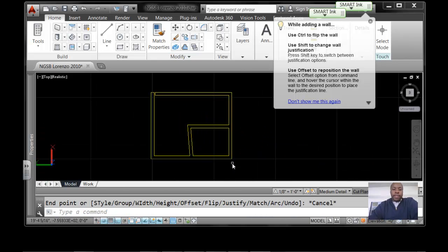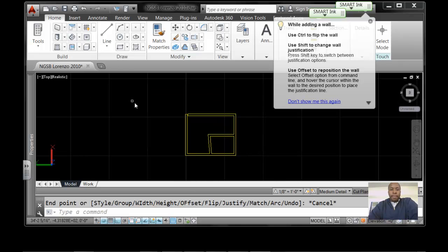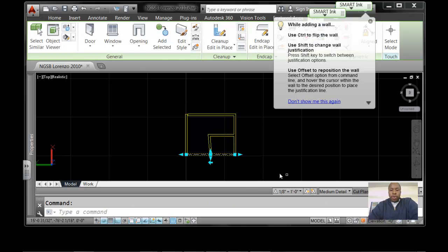There are two ways. There's what some may consider the old way, and then there's what some consider the new way. The first way I was going to show you is called the parametric way. What you would do is you click on the wall, and when you click on the wall object, the top ribbon is going to change. I can click on the two walls that I want to take measurements from.